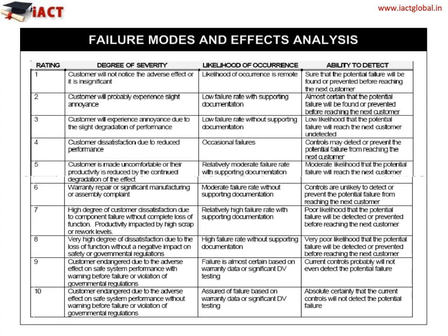Degree of severity, or severity rating, is an indicator from 1 to 10, which indicates the seriousness of the failure mode. As an example, a severity rating of 1 indicates that the customer will not notice the defect, whereas a rating of 7 or 8 will result in high levels of dissatisfaction among customers, and a rating of 9 or 10 can endanger the customer.